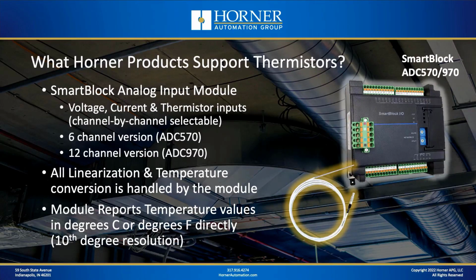They both support voltage, current, or thermistor as inputs on each of their channels, channel by channel selectable. And the module handles all the linearization and conversion to temperature on board. So you don't have to do any of that externally or in your program. And the temperature values reported by the module are in degrees C or degrees F, in 10th degree increments.